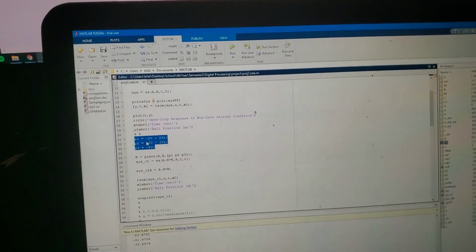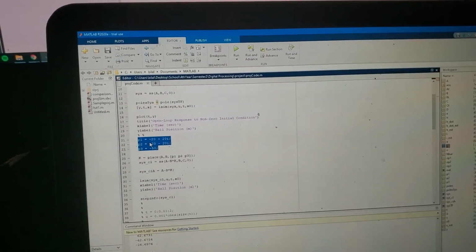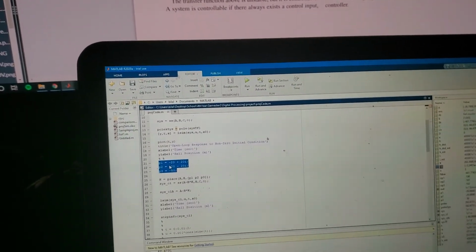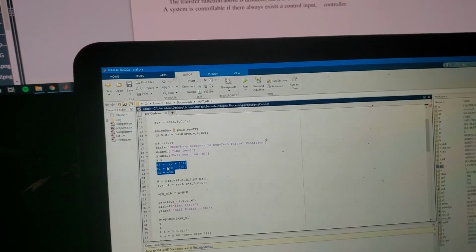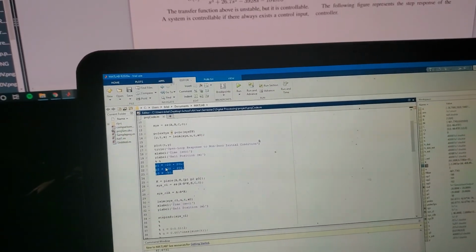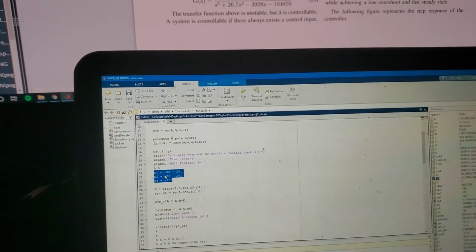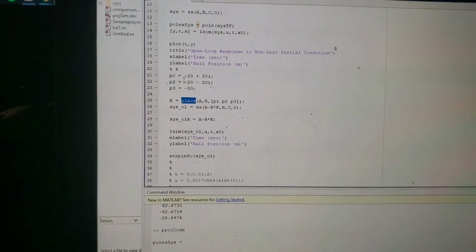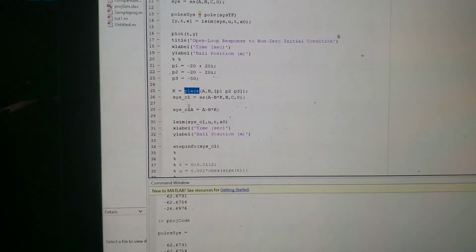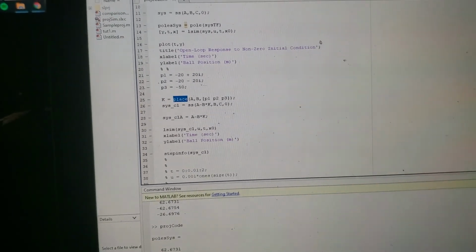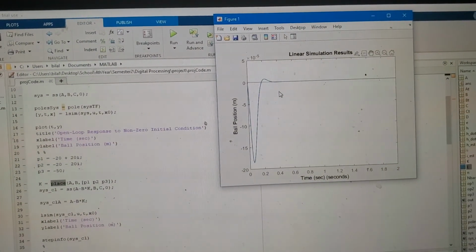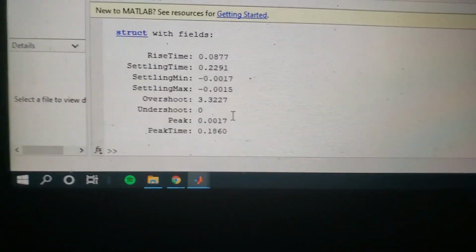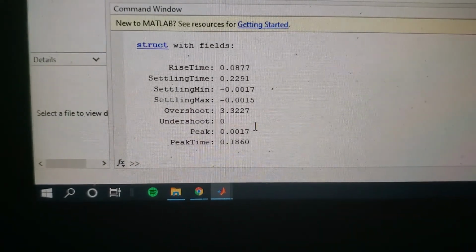Those specifications include an undershoot that's less than 5% and an overshoot that's less than 5%, and a settling time of less than 0.5 seconds. We thought that this would be the best to model the system around, and that's what we did here. As you can see, we use the place function using the poles that I mentioned before. And using those functions, we can see that the system becomes stable now at 0 with these specifications right here, which meets our requirements, so it's a good go.